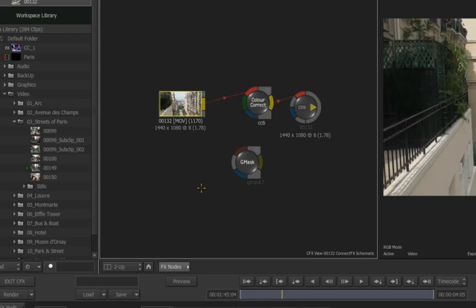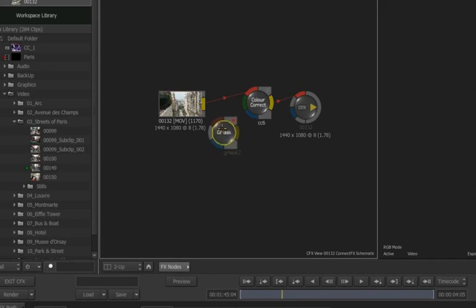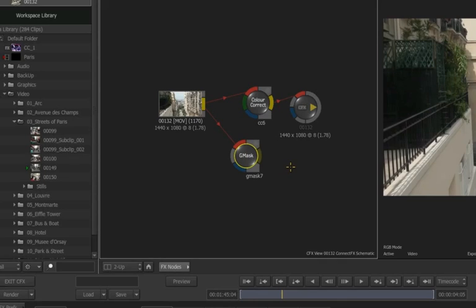Another great hotkey to learn is using the Option or the Alt key when you want to make your connections. This is known as the auto link inside of Smoke. If I hold the Alt key and I take my garbage mask and drag and kiss or touch the two connections, you'll notice the connection is now made.